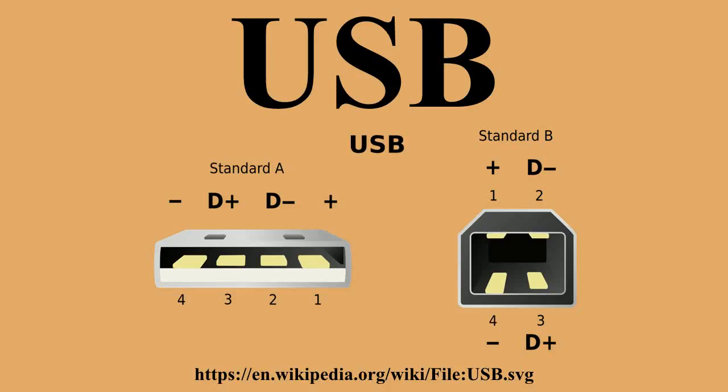After reset, the USB device's information is read by the host and the device is assigned a unique 7-bit address. If the device is supported by the host, the device drivers needed for communicating with the device are loaded and the device is set to a configured state. If the USB host is restarted, the enumeration process is repeated for all connected devices.